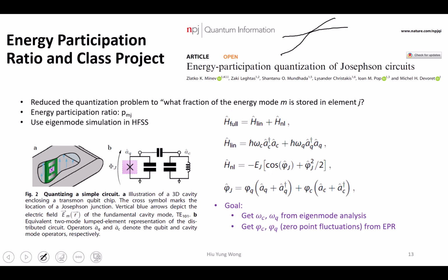Yeah. So last time, some of you kept increasing the meshing, right? This is the number of passes. And then you look at the eigenfrequency, right? And one of you told me that, hey, suddenly it goes up, and then this one goes the other way. That looks like repelling each other, right? But I think this is just because the resolution was not good at the beginning, and eventually it turned out your transmon actually has a larger mode frequency than the other one.